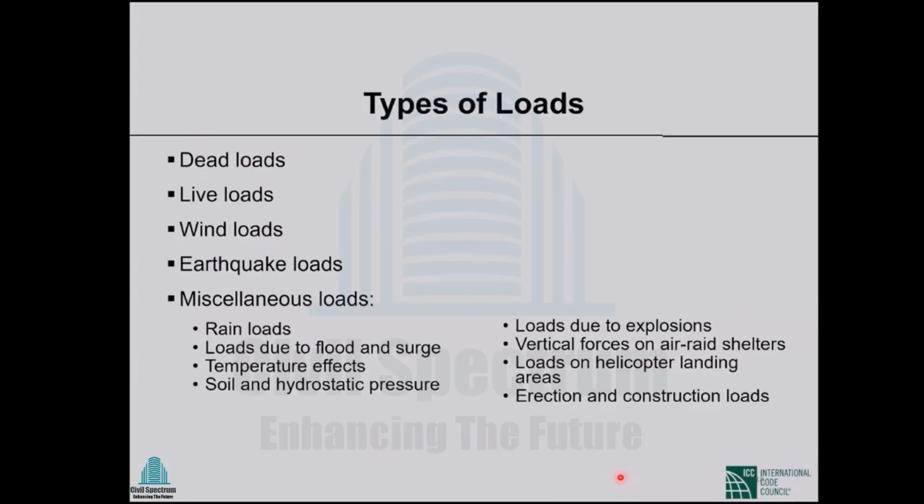So what are the loads? Dead loads, live loads, wind loads, earthquake loads, and miscellaneous loads. Miscellaneous loads like rain loads. Do you really calculate rain loads? Please check what the code says. Loads due to flood and surge. Do you consider that? If you're designing a structure in the coastal areas, you should. And please read the code, how to calculate these loads.